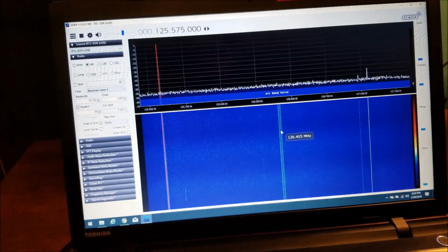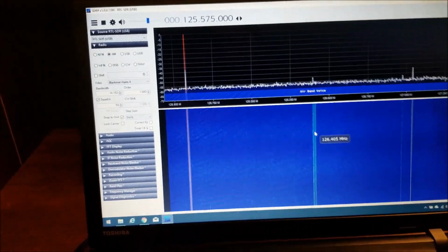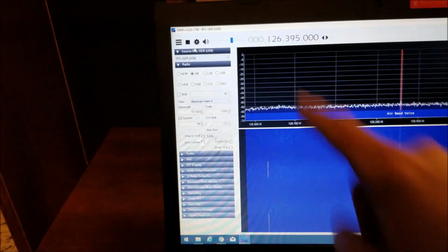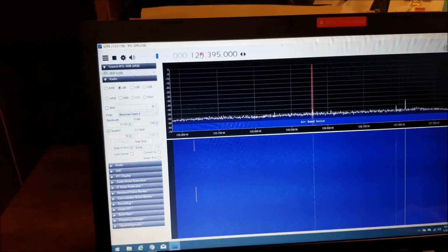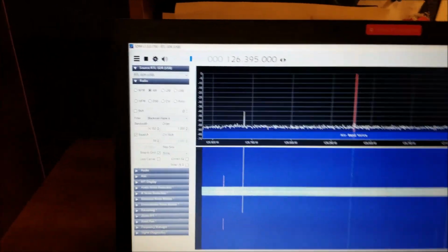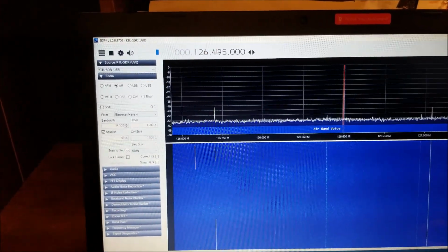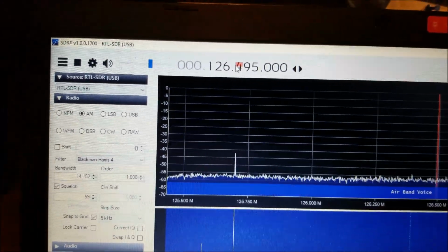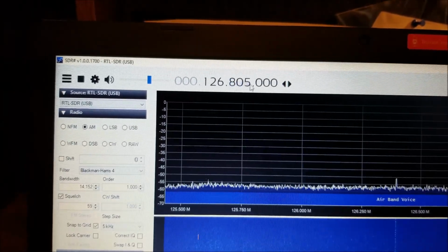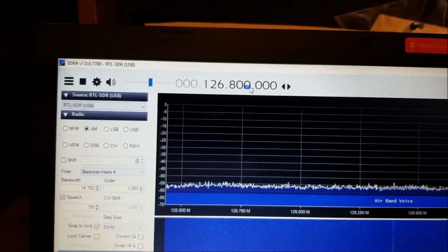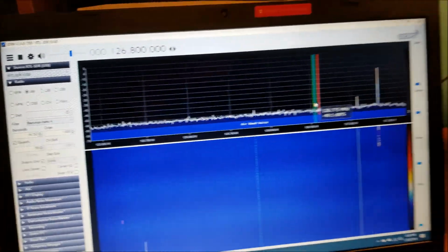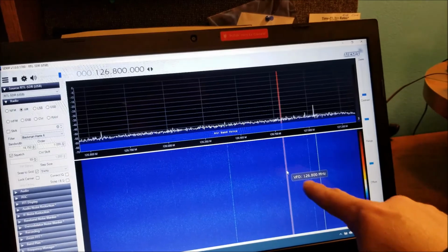We could monitor that for a moment to see what pops up. Nothing. It's not even breaking the squelch. So up here, the local tower at the airport, I believe, is 126.800 megahertz. So 126. Then we're just going to keep clicking it to bring it to 8. Bring that to 0. And make the next one 43210. 126.800. That tuned the line here. We're tuned over here. Yep, 126.800.